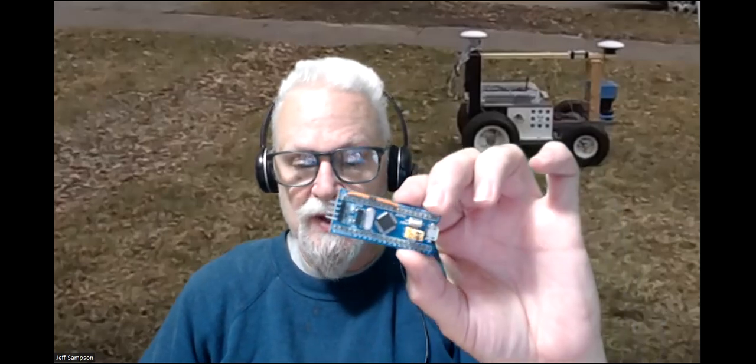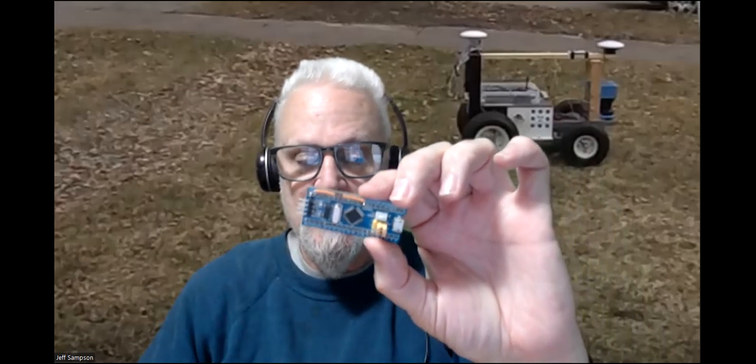So that basically, without pulling it up and showing you all this stuff, my workflow is I say create a new project, tell what processor it is, I pick my peripherals, and then do an initial compile, make sure everything's gonna work. And then I can put in code to blink things, or in my case, read encoders, or I had to initialize the USB because you start with this and do it this way. You've just got the bare processor.